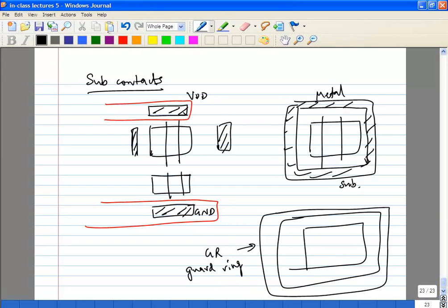So the main idea is, let us say there is a noisy block right next to this block, which is injecting something into the substrate. You want to pick it up before it reaches your sensitive circuit. So in that case, you would put something like a guard ring. If you have a noisy thing, it will get pulled up through the metal and go straight to ground, which is through the low impedance path. Typically a substrate ring will prevent your circuit from injecting noise into the substrate. A guard ring would protect your overall block from picking up things.